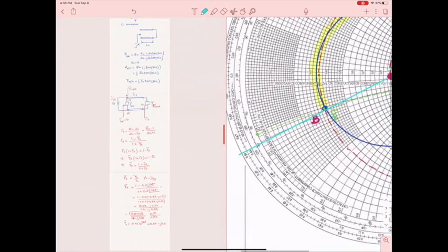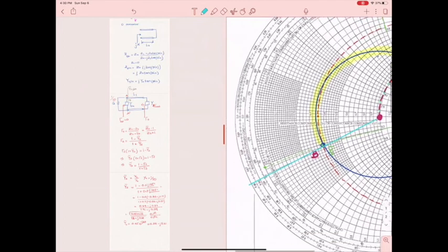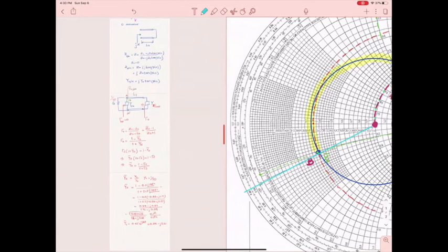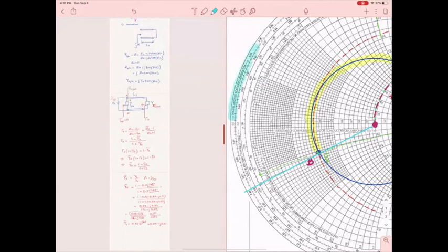And you look at where, you remember that we are traveling towards the generator always. So look at the wavelengths along the generator, and everything that you read is on the outer circle. It's like on this one. Everything you read is on this circle, all right? Towards the generator. If we were to go towards the load, it's the lower circle. So I have to look all around this circle and come and read the value here. And the value here is this one.